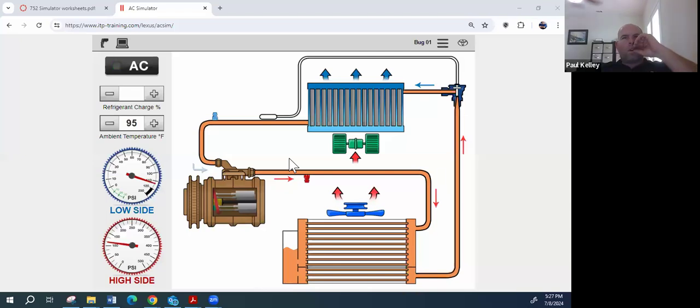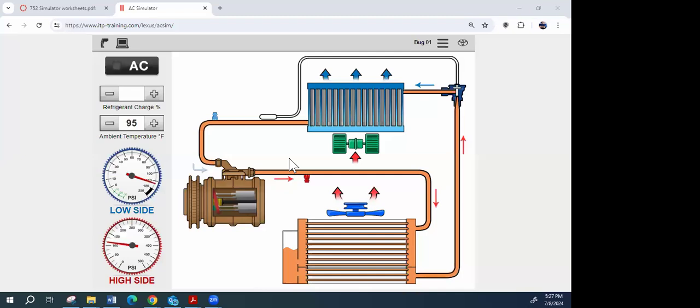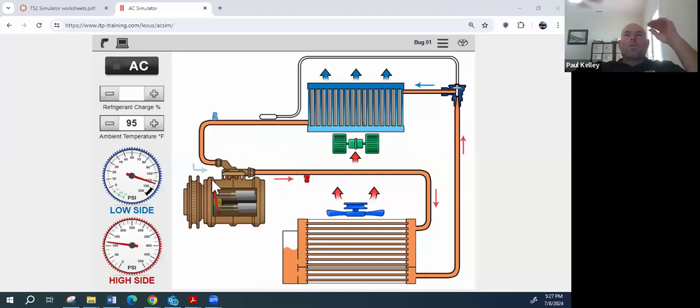Anything that's a little more to the point, right? Because you want to eliminate a lot of things in one swoop. You can check the relay, I agree. You can check the fuse, I agree. But you could check something that would have checked both of those. We can test the compressor if it's getting voltage and ground, so power and ground, right at the compressor. That kind of makes sense to me. You could go ahead and do that.